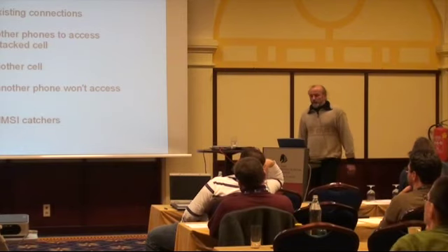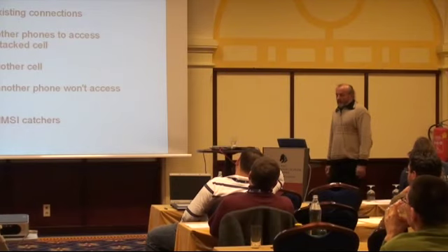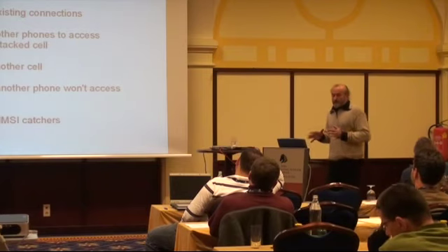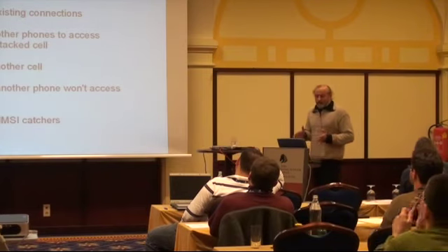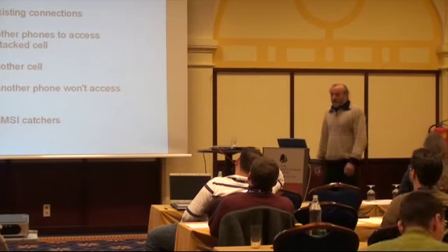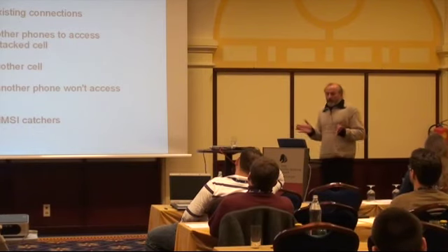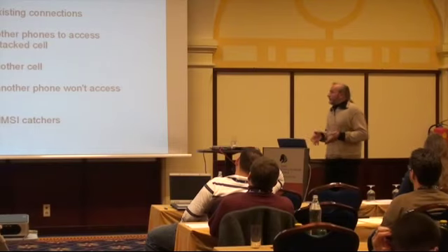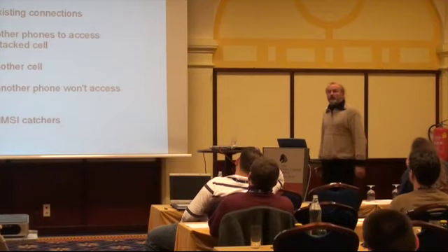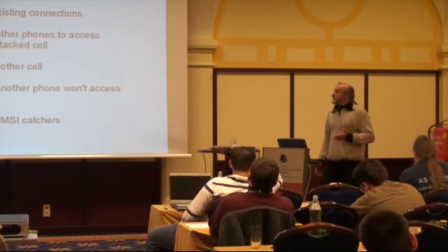There are certain patterns which allow to detect that an IMSI catcher is trying to catch a phone. One of the obvious things for a phone is there is no encryption in use if an IMSI catcher wants to talk to a phone. So if the phone detects, okay, there seems to be an IMSI catcher in place and wants to get me, a modified phone software could ask the user, do you want to deny the IMSI catcher and send continuous RACH bursts to him?